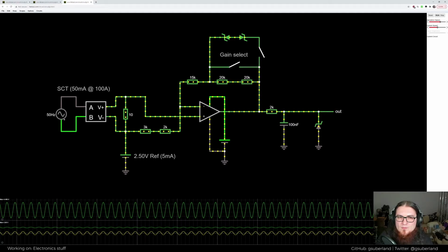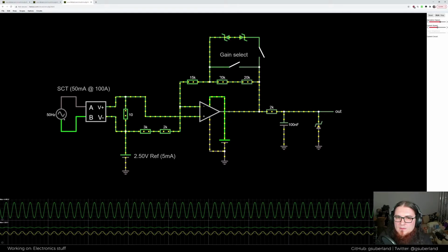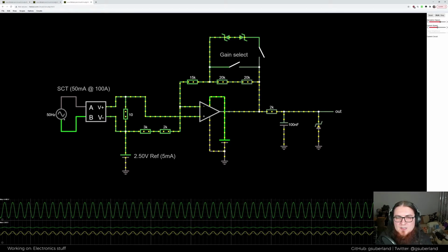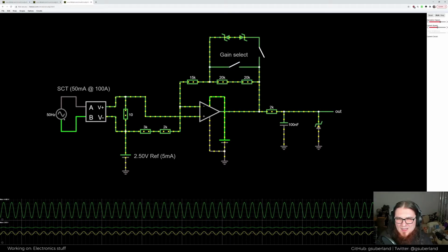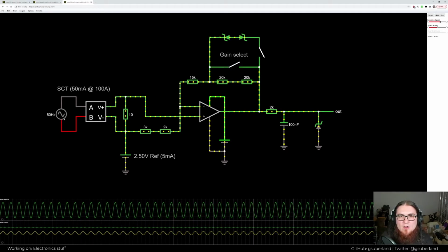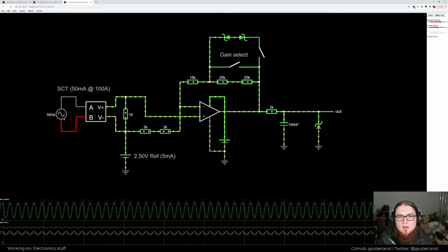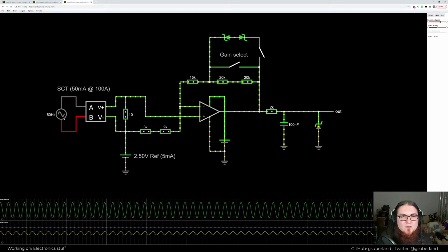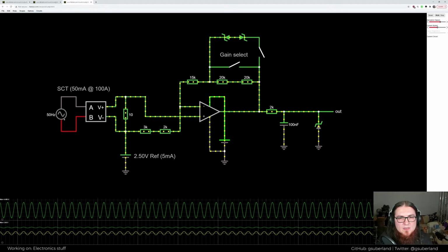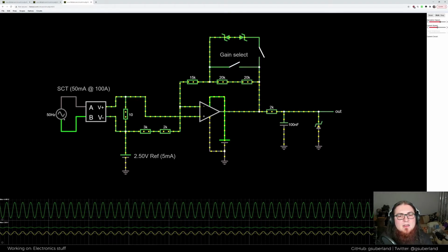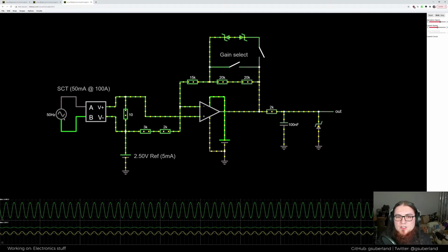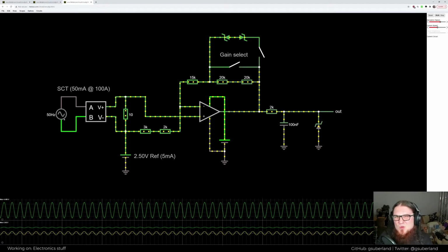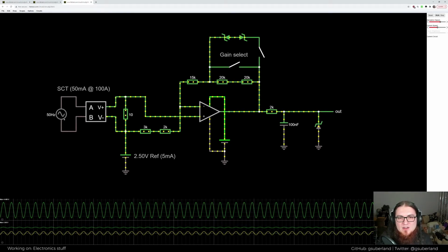And when you work that out, in my original design, these resistor values were twice as high. So this was 40k each, so you had 80k here. And when I worked it out, that actually generated a resistance error of about 3.25%. And that's quite high. And not only is it quite high, it's also non-linear, because this is not a resistance, it is a leakage current. So as the voltage changes across here, the effective change in resistance over here also changes, which is a little bit nasty because it creates this non-linearity.